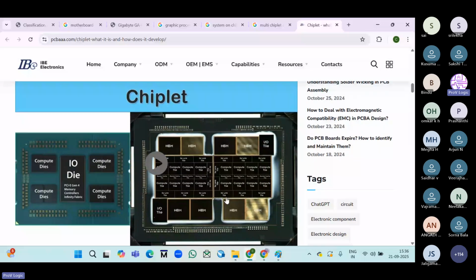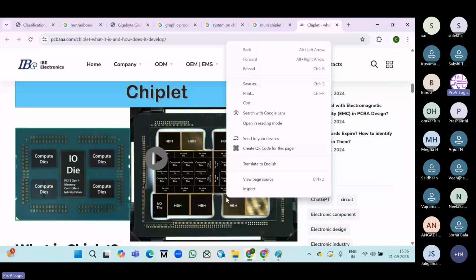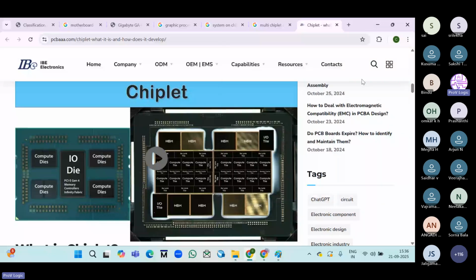Only in SOC, and that too monolithic means it just has one chiplet, one die. In that die, there will be a processor, a graphic processor, IO peripherals, everything. But chiplet means one die is divided into different cores, CCX1, CCX2, like that, and it has separate core dies and an IOD. That's the difference in SOC. There will be a lot of different chiplets.